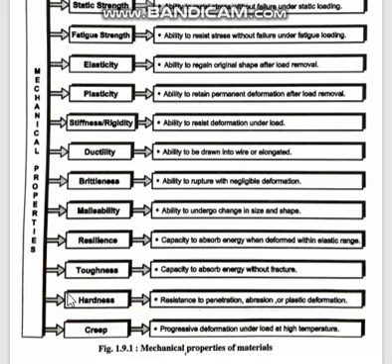I told you where this property is important, especially in the case of cutting tools. Then creep, we have also studied what creep is. Creep is the progressive deformation under constant load for a long duration, maybe at elevated or high temperatures. This is creep. These are some of the mechanical properties that we need to keep in mind.